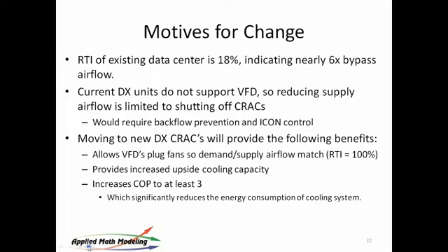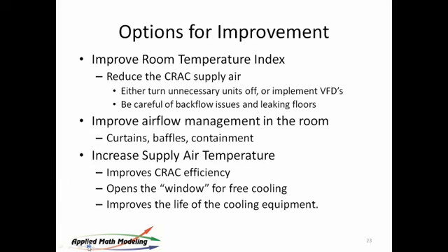And if you were to go to new DX units, there is some advantage because you can put VFDs on new DX units, but I will point out that they don't go down that low. For a data center like this, you couldn't get rid of the amount of airflow you need to get rid of because they only move down about 20%, in my experience. And modeling can allow you to understand, of course, the effect.